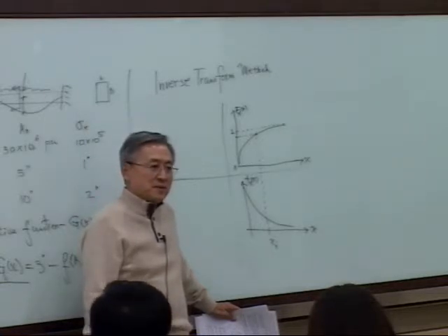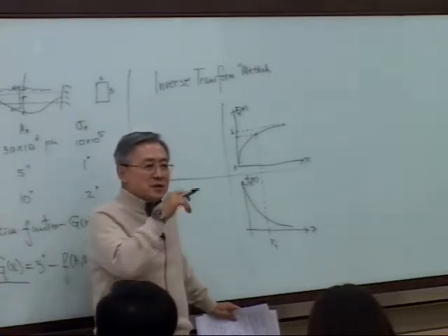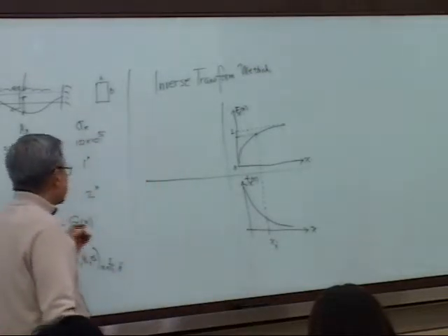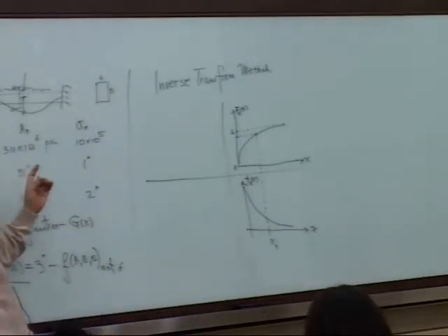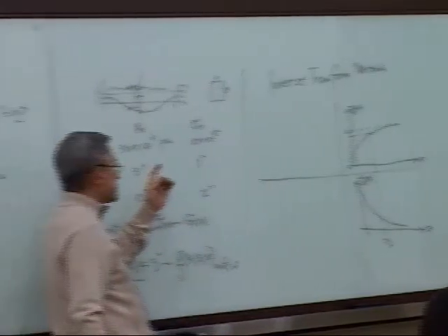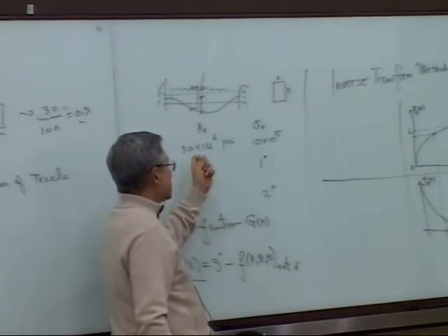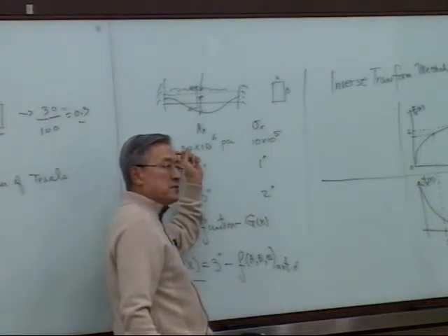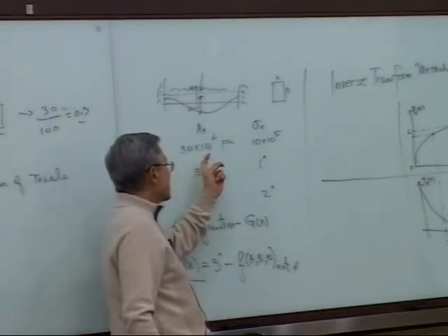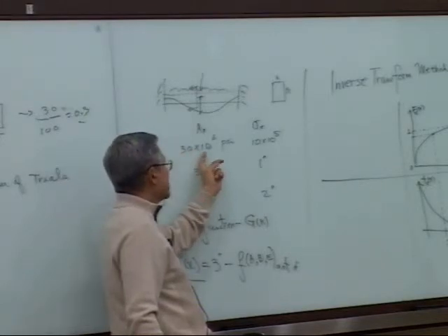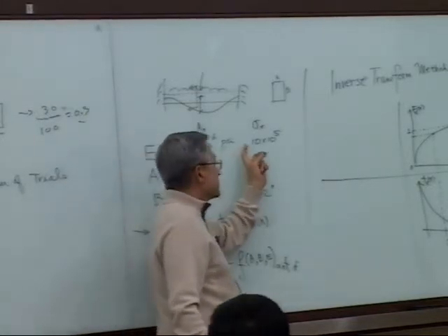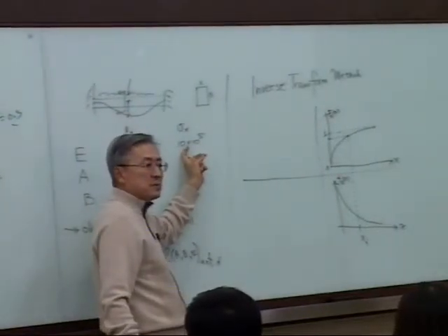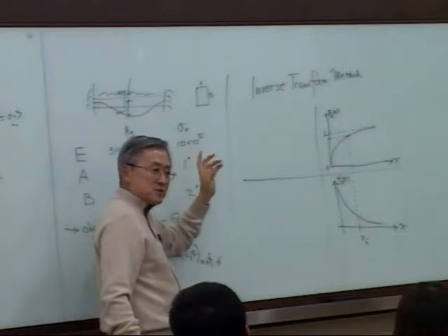It's a random number. You need to generate a random number. Once you generate the random number, which is between 0 and 1, to compute the trial value for Young's modulus, what I can do is take the mean value plus the random number multiplied by the variation.